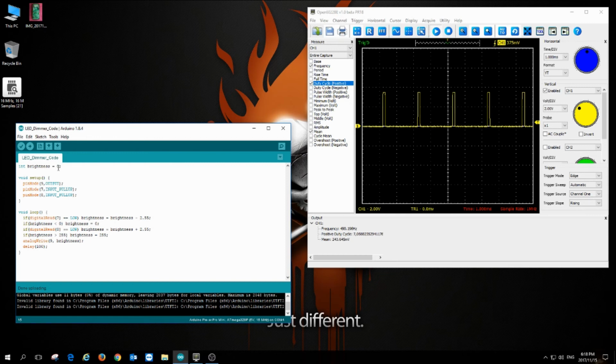Now I'm pushing it 1, 1, 1. It might be making a few jumps and steps, but now if I push and hold, you'll see it'll climb quite rapidly. I'll stop it about there, nearly 50% duty cycle, and you'll see we're halfway through our 3.3 volt cycle already on the mean voltage. If we go all the way up to 100%, you'll see we'll be sitting at about our 3.3. Now the voltmeter on this thing's not dead accurate, but you get the gist of how it's working.